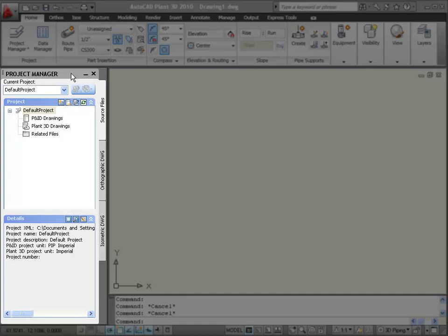The starting point for managing projects is, of course, the project manager. In the introductory video, I talked about how AutoCAD Plant 3D organizes drawings into projects and how the project controls the pipe specs available, allows piping connections to cross drawings, and allows project-wide data viewing, exporting, and importing. The project also controls the annotation styles available, the data fields for each component type, customizations, the organization of objects in Data Manager, and so on.